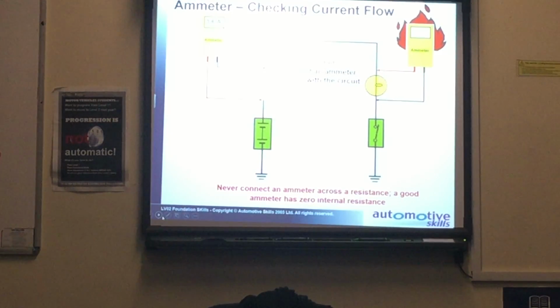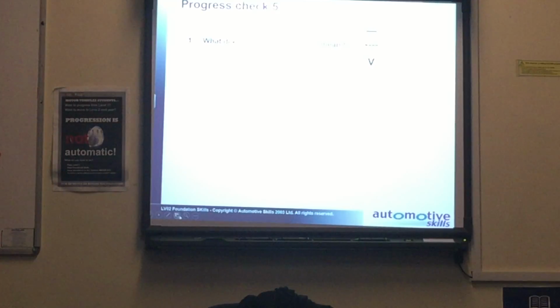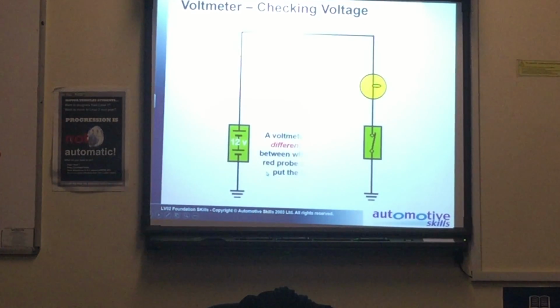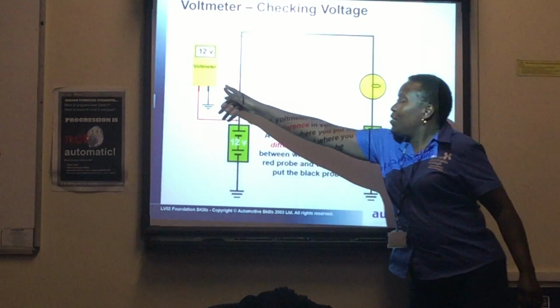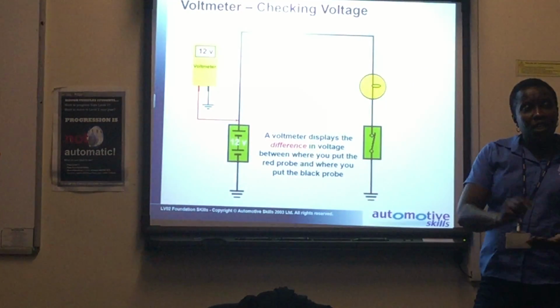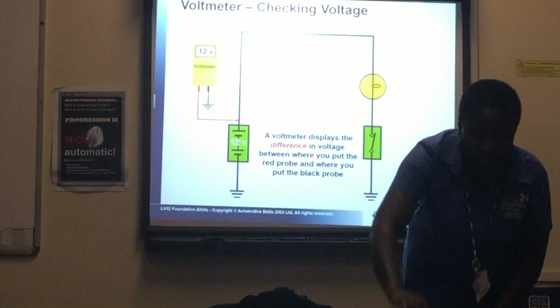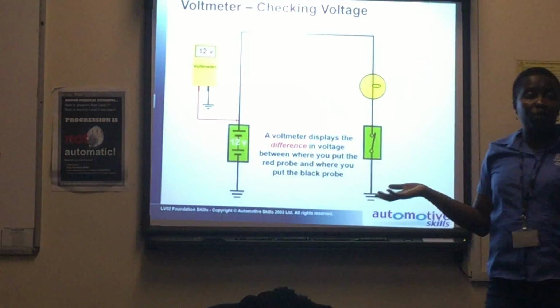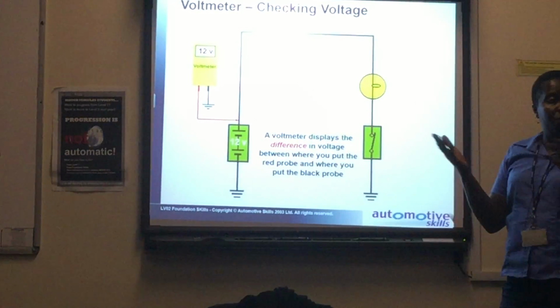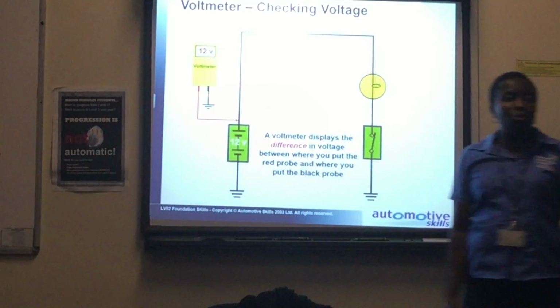If it is voltage we are checking for, we can connect like that. Voltmeter negative anywhere on the car body. This one, just touch the car body. Then the red one there, positive of the battery. We will get a reading of what is coming out of the battery.